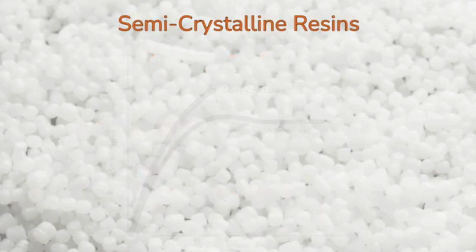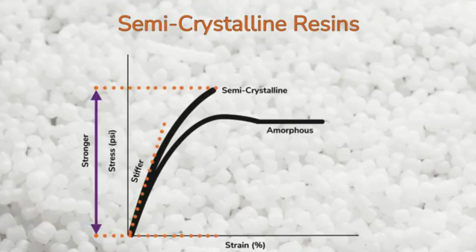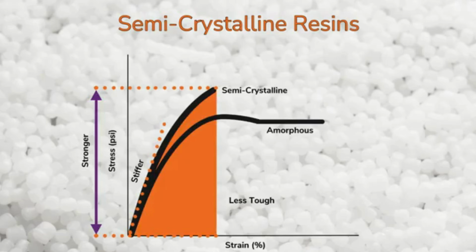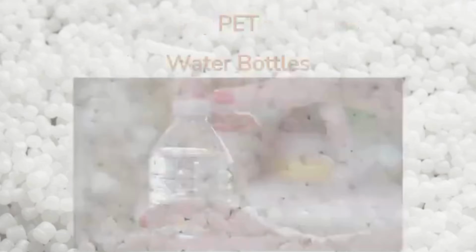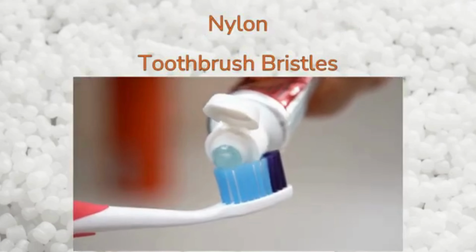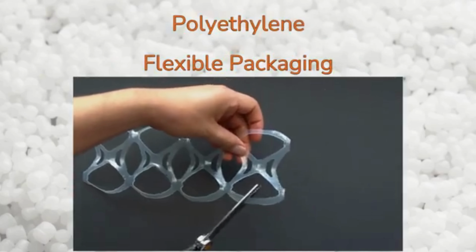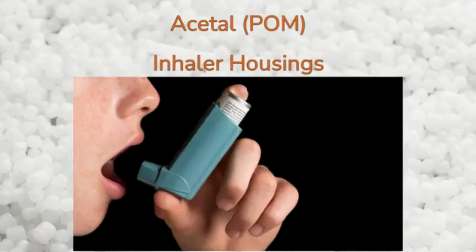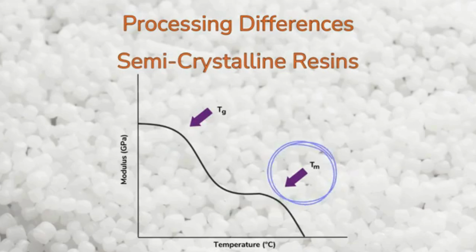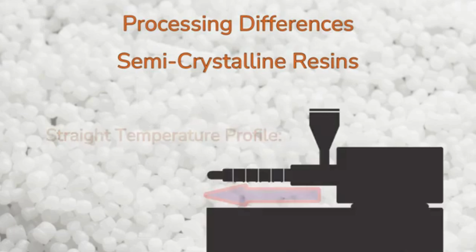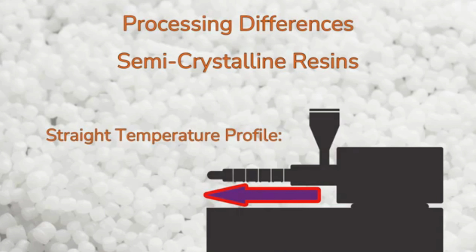In situ small-angle X-ray scattering (SAXS) or wide-angle X-ray scattering (WAXS) studies of PE have demonstrated that crystal slip and cavitation are strongly coupled and depend on temperature and lamellar morphology. Cavitation can produce strain whitening, while subsequent lamellar reorientation and molecular alignment contribute to strain hardening.